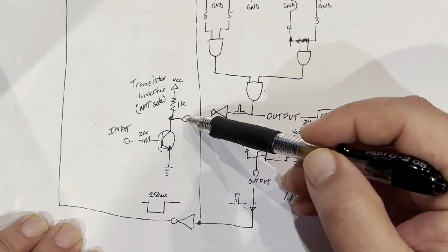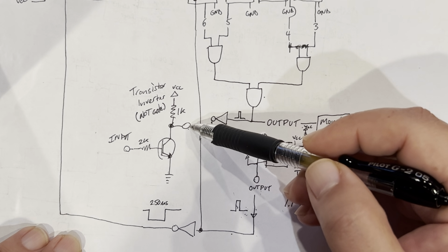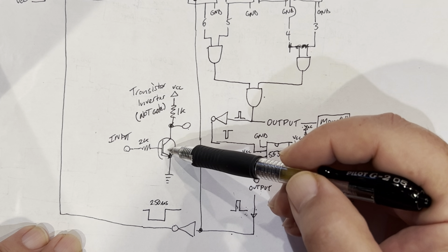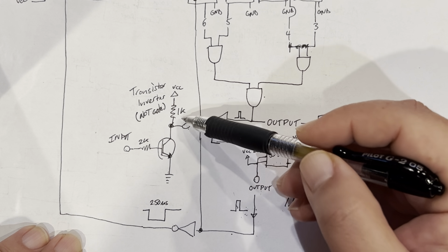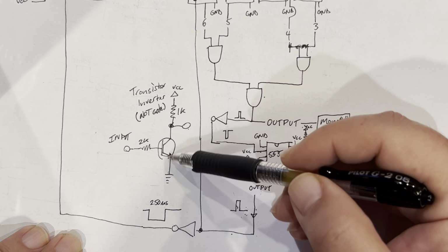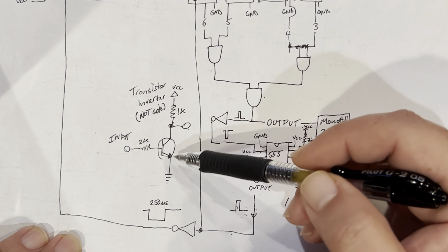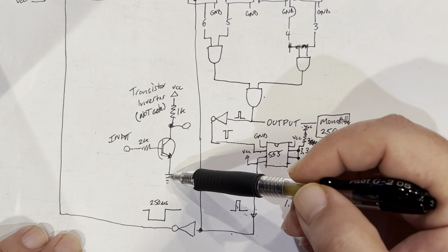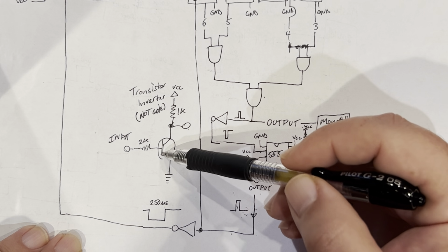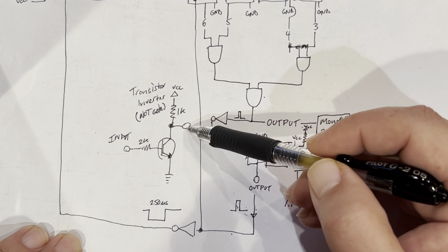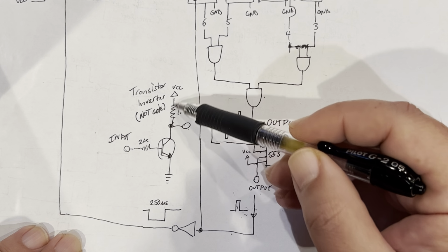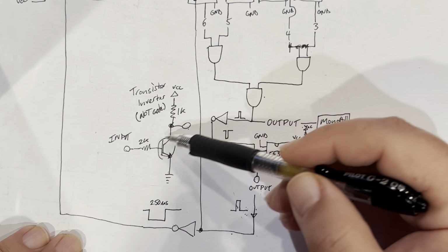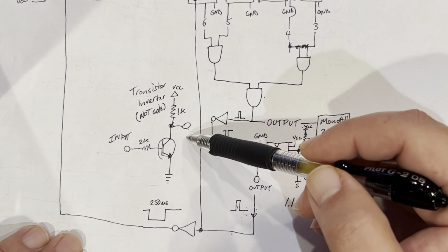And this is basically on until you apply a signal to this. And when you apply a signal to the base, the current flows preferentially down to ground in this common emitter, and this turns off because the path of least resistance is down. And when you cease putting a signal in, this turns on again because the current goes in this direction. And it's a very good functioning inverter gate.